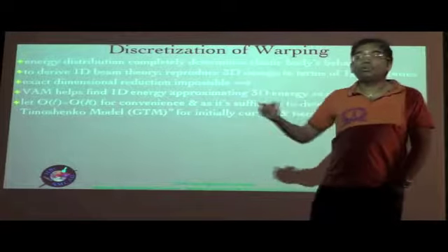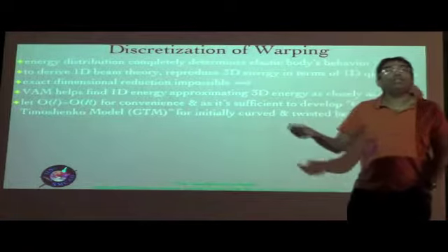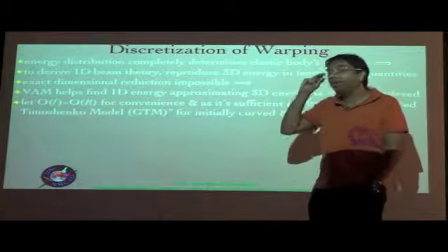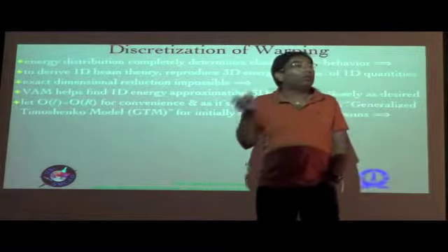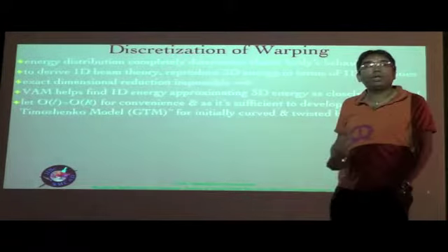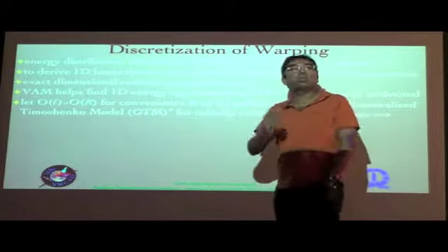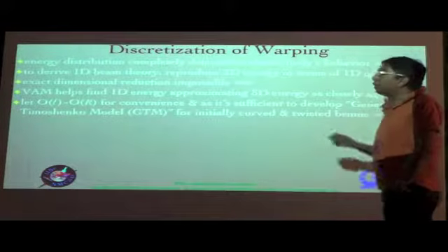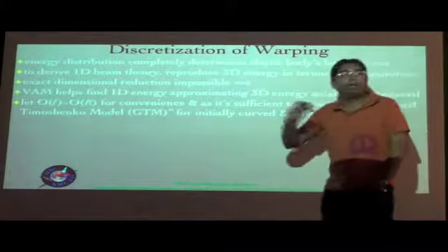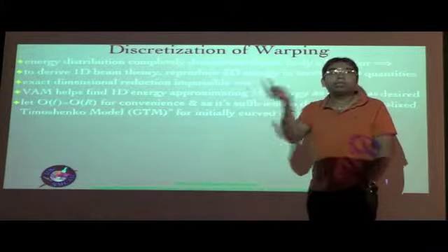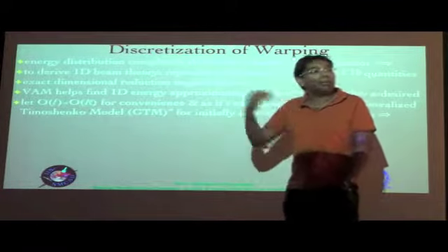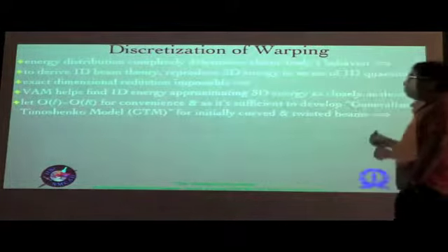Okay, so you know that the classical Timoshenko model, which Timoshenko himself derived and therefore named after him, basically accounts for transverse shear deformations in addition to what is already taken care of in the Euler-Bernoulli beam theory, and therefore lets the normals to cross sections no longer remain normal. So in other words, the normals can rotate separately from the cross section, so that the additional rotation basically constitutes the transverse shear, which we saw can be included in two different ways: either as a part of warping, or as a separate 1D variable, right?